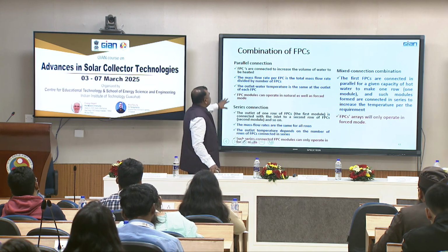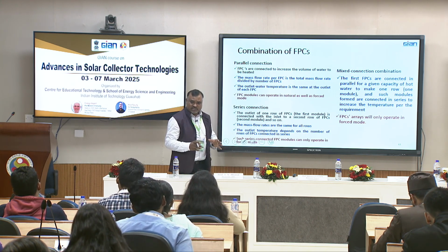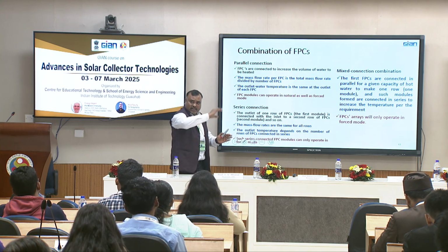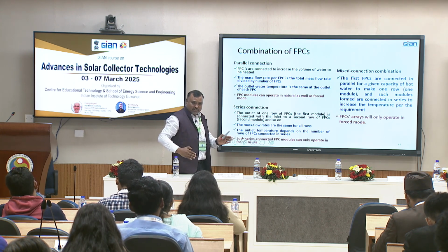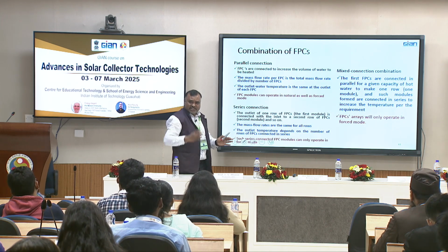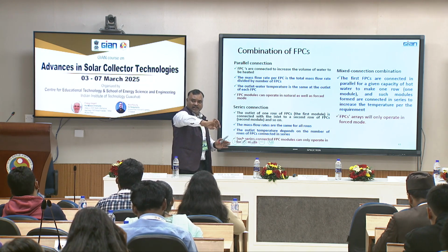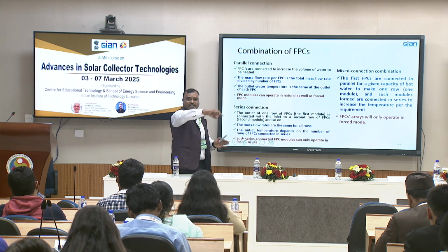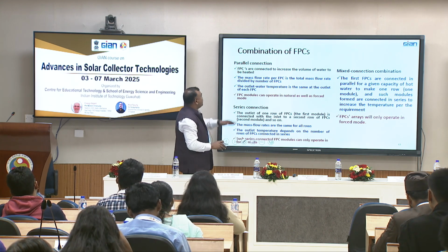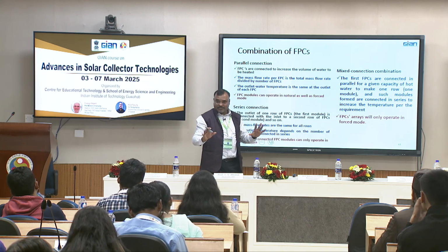These FPCs are connected to increase the volume of water to be heated. Parallel means one after another, right. There is a header at the top. Then all are at the same temperature because they are in parallel. Series means you feed it here and you take it out, and that outlet will be the inlet to the next, and then you take it out, and that outlet will be the inlet to the others. That is the series connection. In parallel connections we are promoting an increase in the volume of the water.